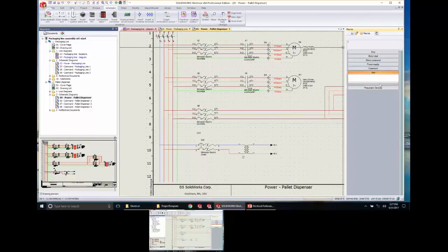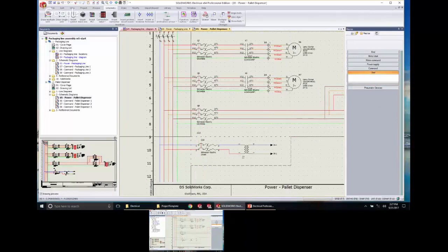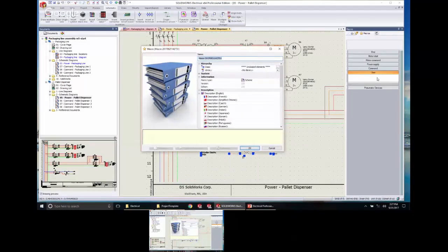And it's really easy to make a macro. Again, you're going to use these groups. I'll use the user one here. Just use your box select for whatever you want to be in the macro, left click, drag and drop it over to that group. It gives it a unique name, and all macros, and I'll say all symbols as well, have to have a unique name.